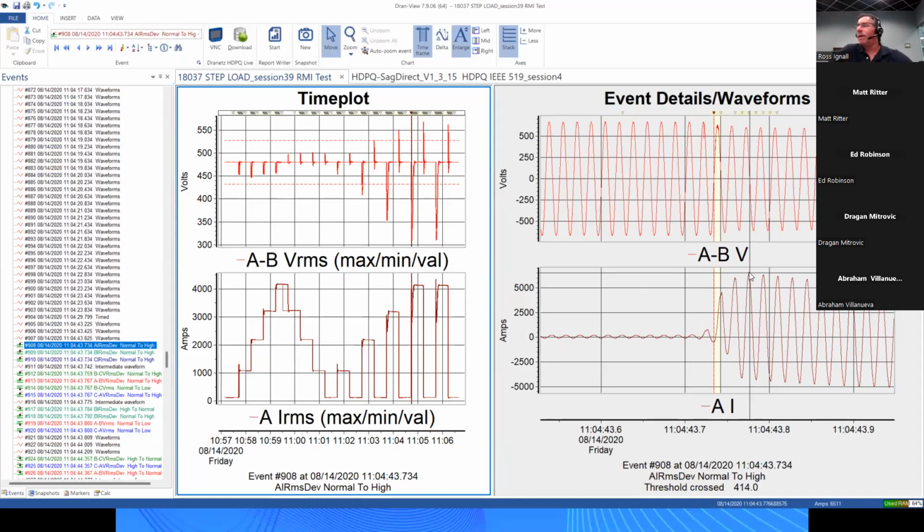When I'm at about 7,700 amps, I'm looking at over here. So you can see how high that overshoot went, and you can see it starts to come down within the nominal to where it's going to settle after that test. And again, that's the big thing that they're looking for: where did it peak and how does it collapse down? And what's the reaction to that impulse? They call it transient testing, but it's not really transient in the terms that we use things.